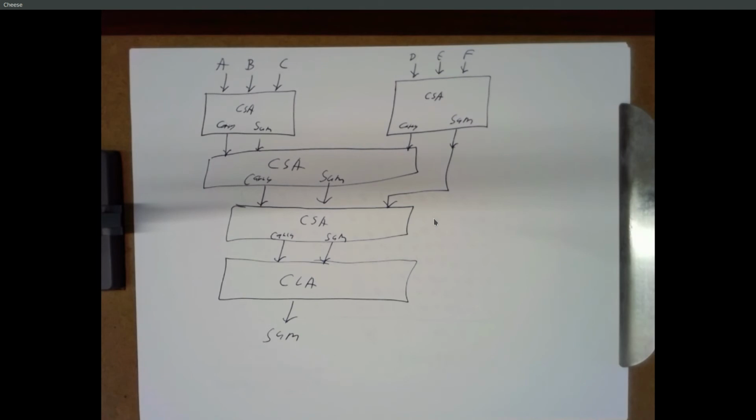And that's a key. I mean, every processor out there uses some version of a Wallace tree or something similar inside the CPU to do multiplication. And it's just one of these speed ups that goes way back into the 50s, the 60s, the days of Big Iron, when IBM and Control Data Corporation and Cray and so on were making their room-sized machines. These were the kinds of things that they were doing in their processors to speed them up. And it's why some of these machines from CDC and some of the architectures Seymour Cray came up with were so blazingly fast. And there's tons of stuff like this that goes on inside CPUs.